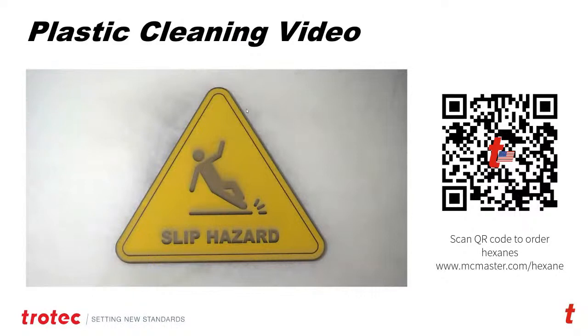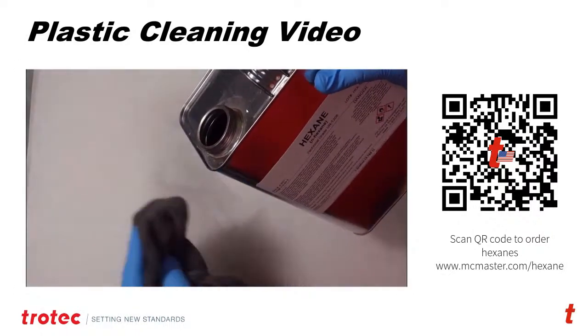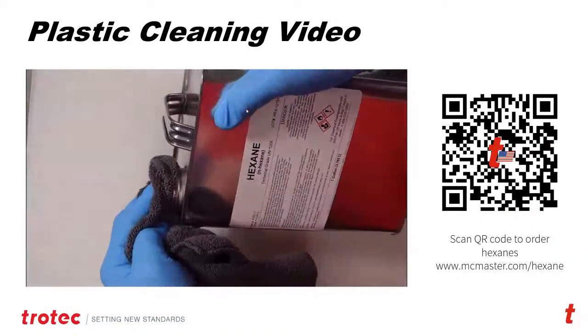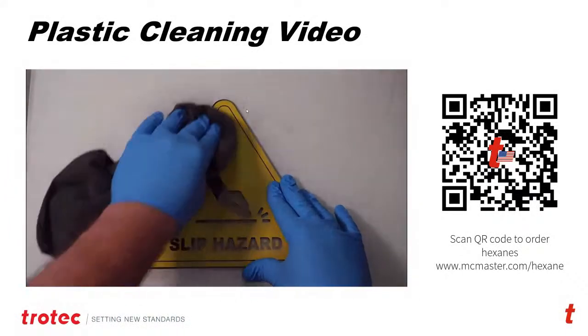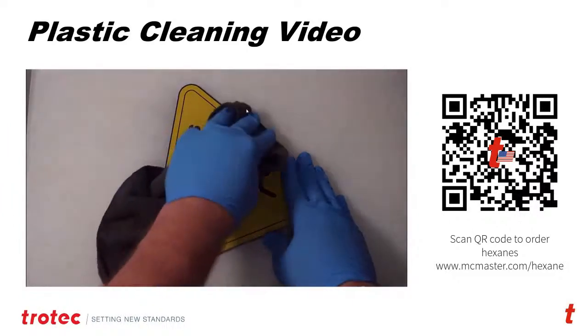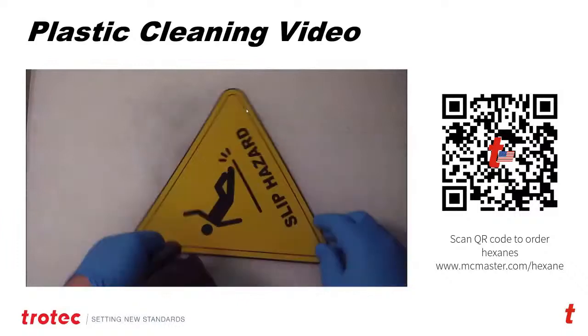Now, in some cases, if you do over engrave it or you have a lot of residue, there are materials that I recommend keeping in your toolbox, and that is hexanes. Hexanes is a great cleaner for this type of plastic because you don't want to clean plastics like this with alcohol. Hexanes are a petroleum-based cleaner, and I do highly recommend keeping them when you're processing plastics.